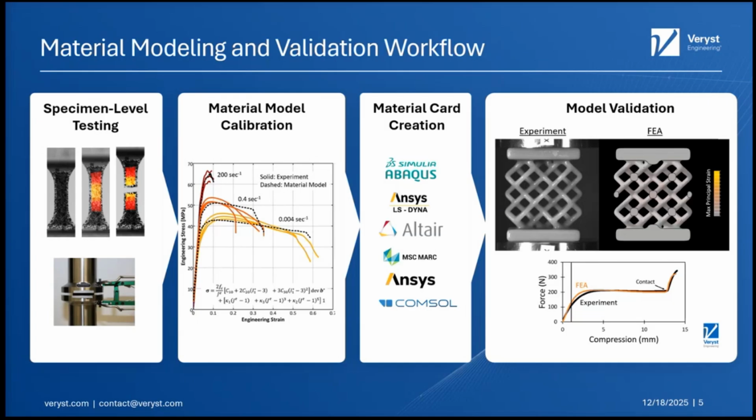One really great example is the old plastic grocery bags that you'd get, which are made out of a material called HDPE. I'm going to simplify it, and the HDPE that you get there is usually multi-layered as well, which makes it a little more complex. But they make those very thin sheets by taking a big piece of HDPE and extruding it. That extrusion is applying force and making it thinner and pulling it in the tensile direction. So that means that you've aligned those polymer chains and you get a much stronger response. So if you take that same grade of HDPE and injection mold something versus the bag, the bag is going to show a much higher yield stress than the injection molded HDPE because it hasn't gone through that mechanical working.